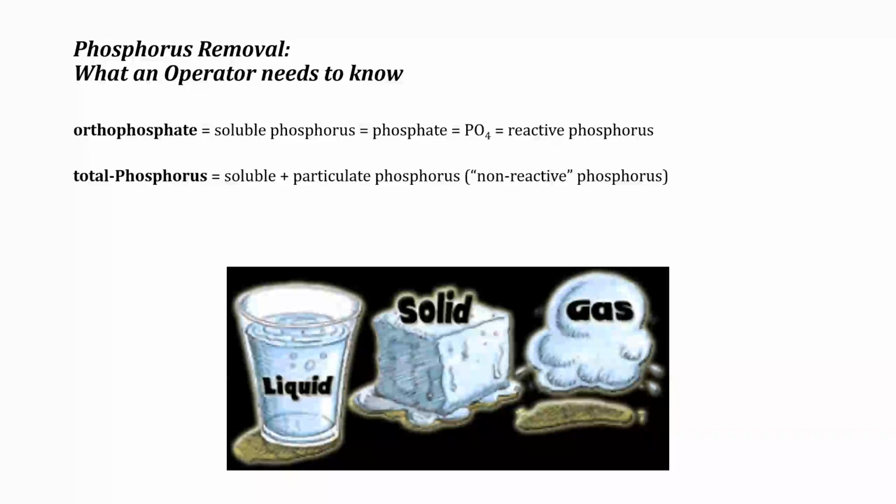But the soluble phosphorus, there's a number of types of soluble phosphorus, but unless your permit limit is below 0.1, which I don't think anybody's talking about anything like that, the overwhelming percentage of the soluble phosphorus is orthophosphate, 90+%. So we concern ourselves with orthophosphate, which for all practical purposes is the same as soluble phosphorus.